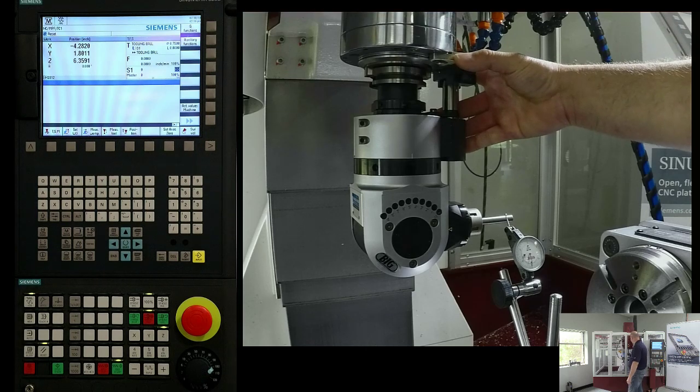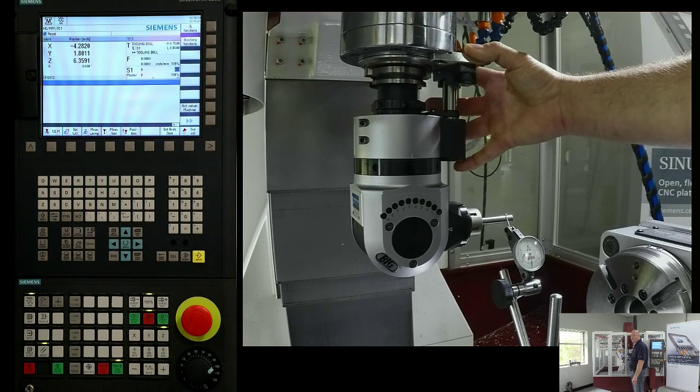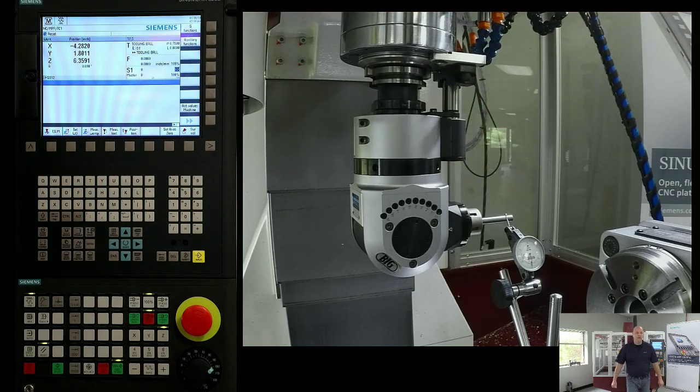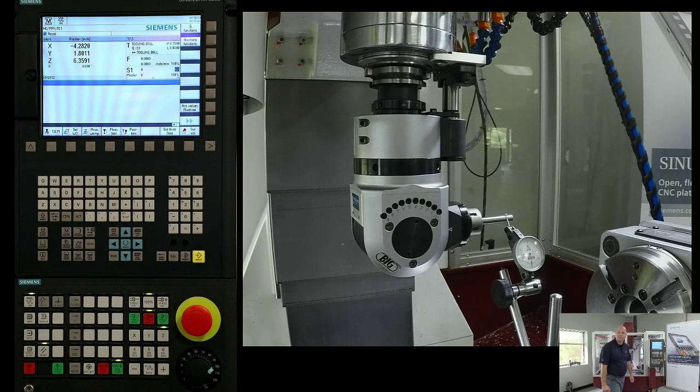So once I've done that, and I mechanically got the head physically in the machine spindle, now it's time to actually find some of the key numbers I'm going to need to know. And what do I need to know about this? Well, when you're setting up these type of heads, you do have to set up the machine with what we call a positive tool length offset strategy. So what that means is my tool lengths will be measured from gauge line of the spindle or spindle face. I commissioned this machine to be spindle face to the tool tip.